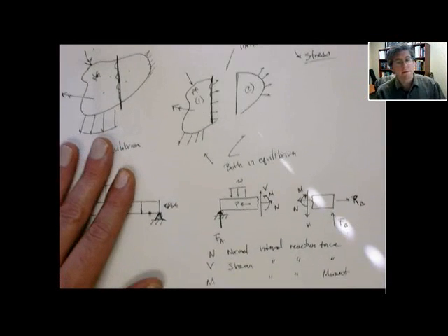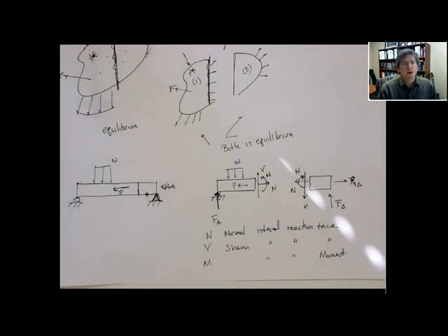The book also talks about internal reaction torques. The units of moment and torque are the same, and the way you decide whether something's a torque or a moment, you have to consider the geometry. Technically, they're the same. The units are the same. They're both the moment arm crossed with the force vector, but they have a little different connotation.